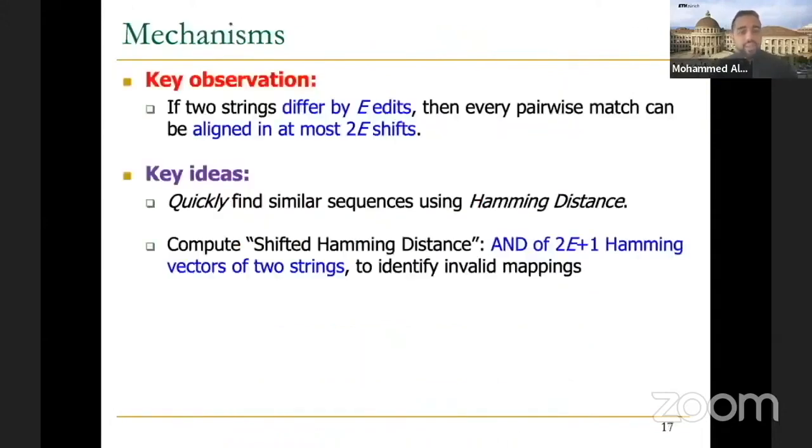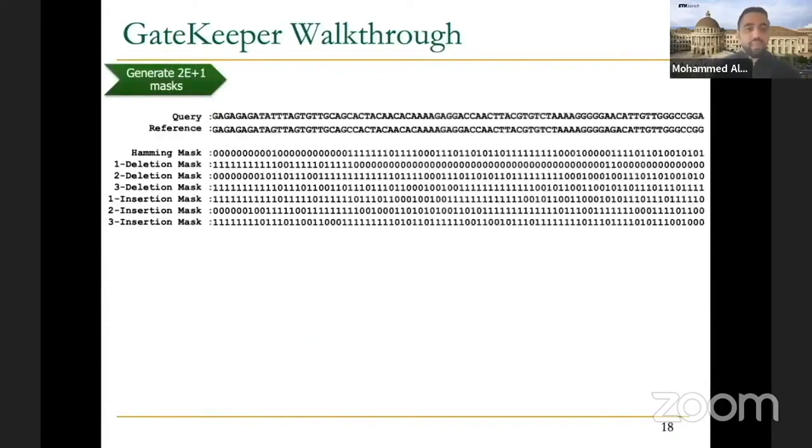All right, so that is the algorithm. And now for the implementation, or how we really implement it on FPGA or on logic gates. So first, let's see a real example with real data. This is the real sequences from a human genome. And what we need to do, this is the Hamming distance calculation, just XOR between the two sequences. Let me annotate it. So these two sequences, and we do first the Hamming distance calculation, just XOR between them, right? And you can see it's 0 where they exactly match, 1 where they don't match in the corresponding locations.